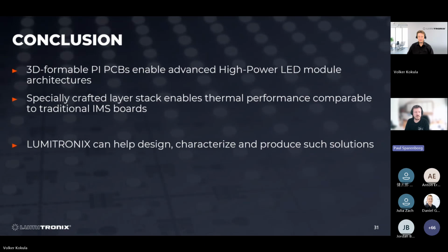One aspect we would like to highlight is that not only the PI layer or the dielectricum layer in the aluminum PCB is important to consider when choosing the stack up of your PCB design, but it is also very important to consider that in most PCBs, glue is used to laminate the layers together, and this glue can have significant thermal resistance.